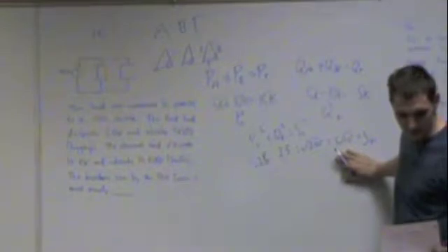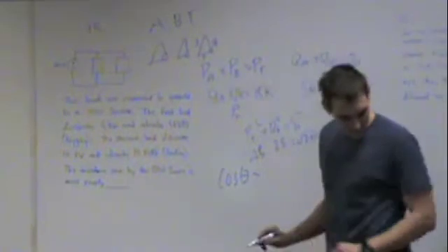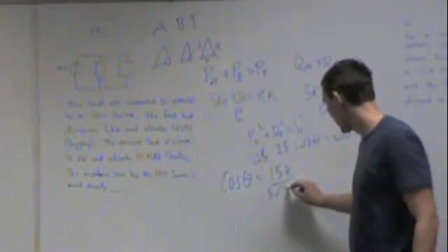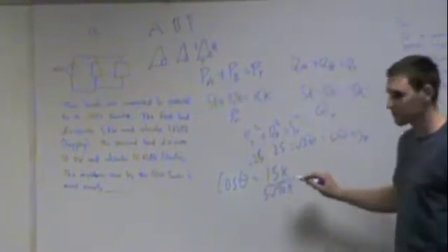So this is the magnitude of our power phasor. So after that, we're then going to find, we have cosine of theta, which is the power factor, equals 15k, which is P, over 5 radical 10. Okay. With me still, guys?